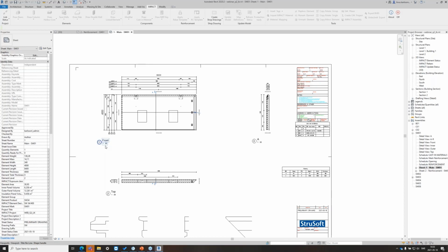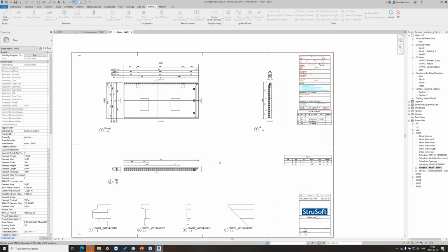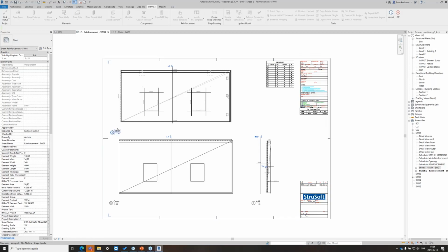So here we can see that the scale that we ended up with was 1:35. And if we think that this is a little bit too little, because we have a lot of space here that I haven't used, we can create the view for this front a little bit bigger and reorganize a little bit. But I think that you get the point here anyways. So 1:35 on the main drawing, and since we don't have that many dimension lines here, we ended up with 1:20.